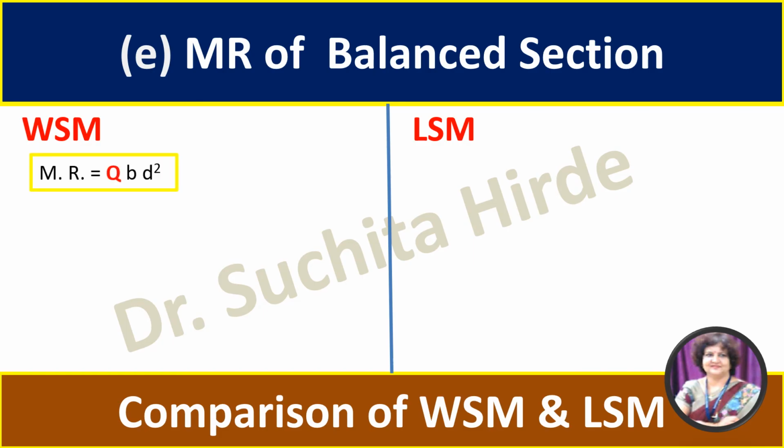In working stress method, moment of resistance is calculated using this formula: MR is equal to QBD square. In this we equate moment of resistance to bending moment and we decide the depth of the section. In limit state method, the formula is K FCK BD square. Now if you compare both formulas, in both there is BD square, whereas in working stress method there is Q, and in limit state method there is K into FCK.